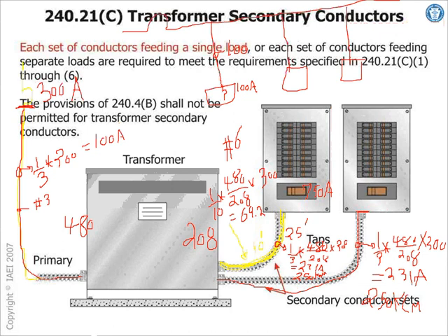So to summarize, guys, there's one rule. If you tap the secondary only for 10 feet, and if you tap the secondary only for 25 feet, there's another rule. If you tap the secondary and the primary for 25 feet, not 10 in this case. It doesn't make sense for 10 primary, secondary, right? Not a whole lot of juice, not a whole lot of length. 25 feet, primary plus secondary. You can see the rules.